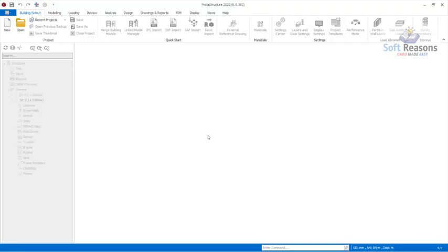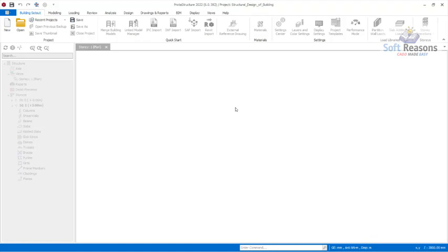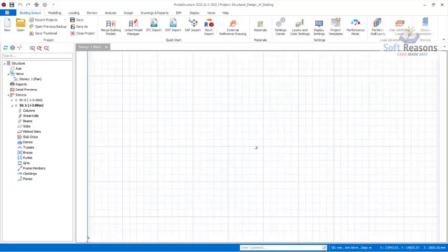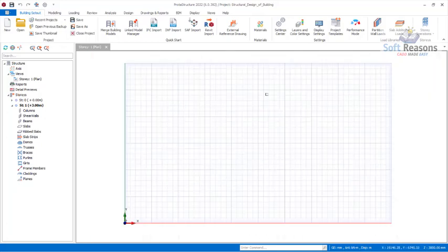So this is the code we are going to be using for the structural analysis and design of the building. Successfully, the code template is ready. Okay, what you have to do now is navigate to the modeling tab, but by then in the building setup tab, presently we have to import the AutoCAD file we saved to the desktop by clicking on the DXF import.